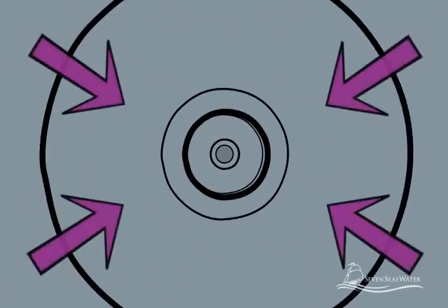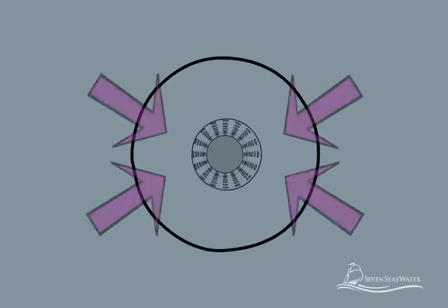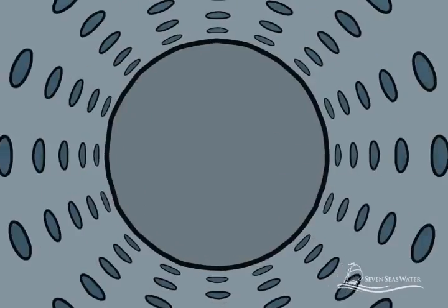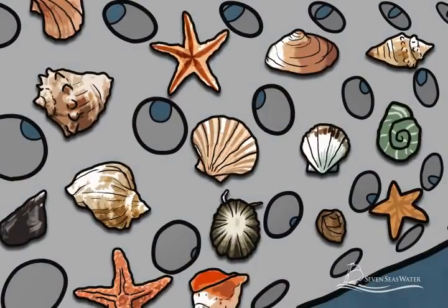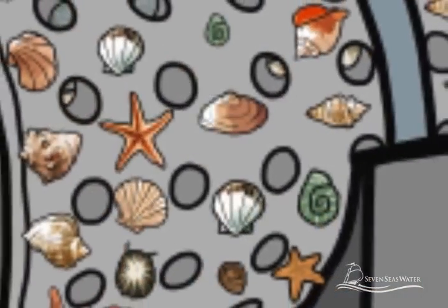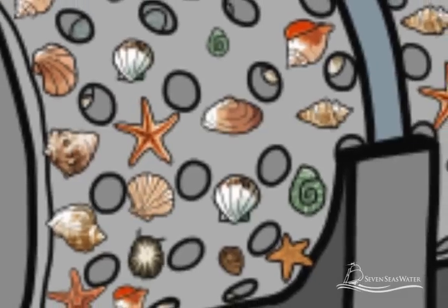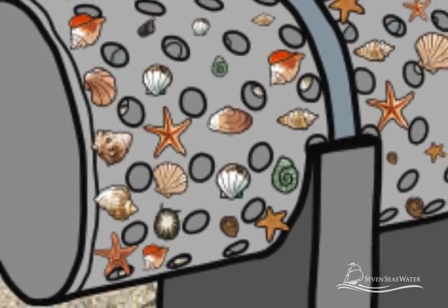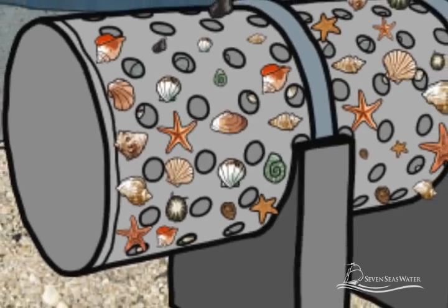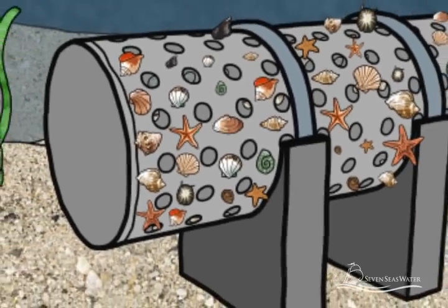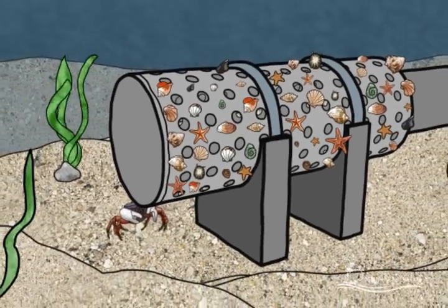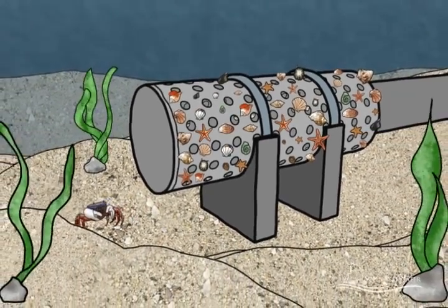The concentrated salt stream is sent back to the ocean through a brine disposal well, or a device known as a brine outfall. The brine outfall is situated in an area of significant ocean flow so that the salt levels are quickly returned to equilibrium with the ocean. The location for the outfall should contain no sensitive marine ecosystems. In a properly designed brine outfall, no noticeable increase in salinity can be detected at a distance of a few meters from the discharge.